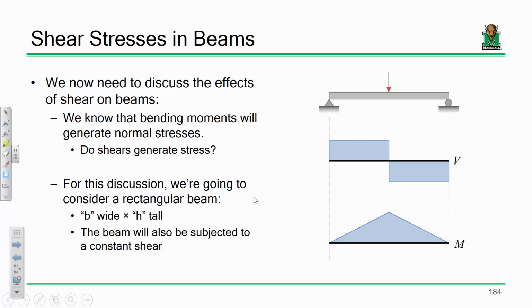That doesn't happen in a solid beam. In other words, imagine if I took these pages and I superglued them all together. The beam would get a lot more rigid, right? And what's going on between those pages? That glue is sort of keeping the beam together. So that interface between those pages is seeing shear stress. And that's what I'm trying to determine in this derivation: what is that shear stress in a beam?